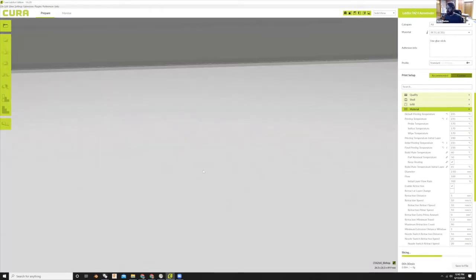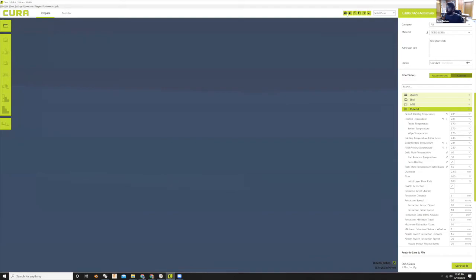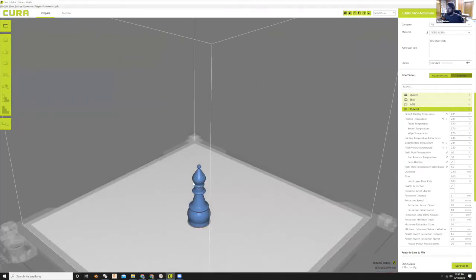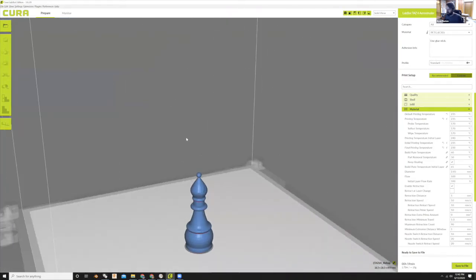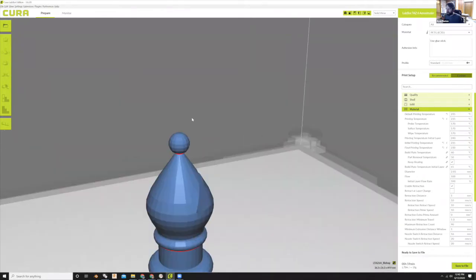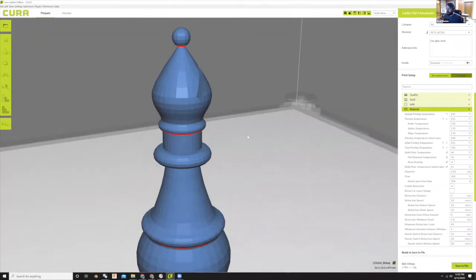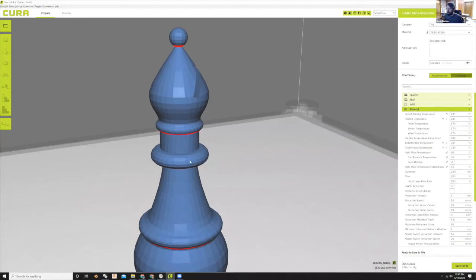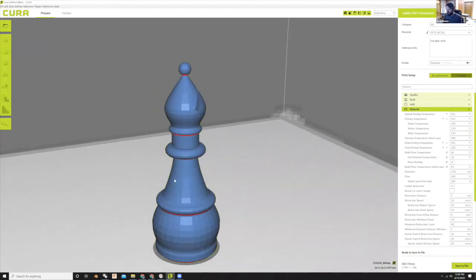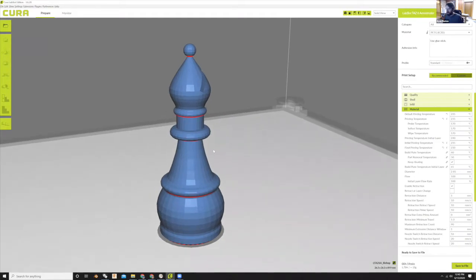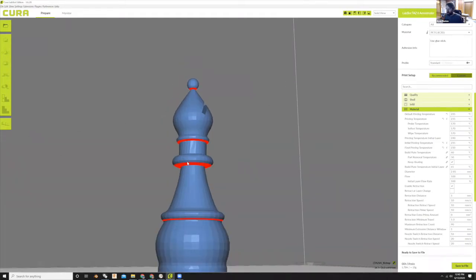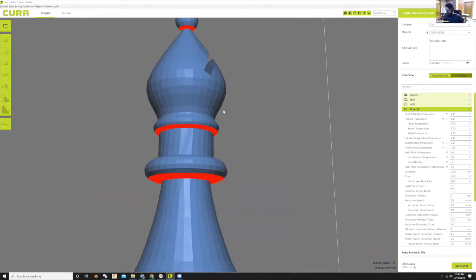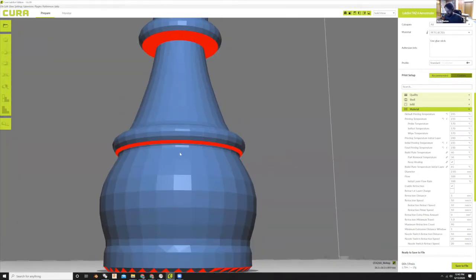This is something I do want you to see. So this is how it looks rendered with the medium density polygon. And you're getting some red warnings here. These are for overhangs. This is something to think about when you're designing for 3D printing.